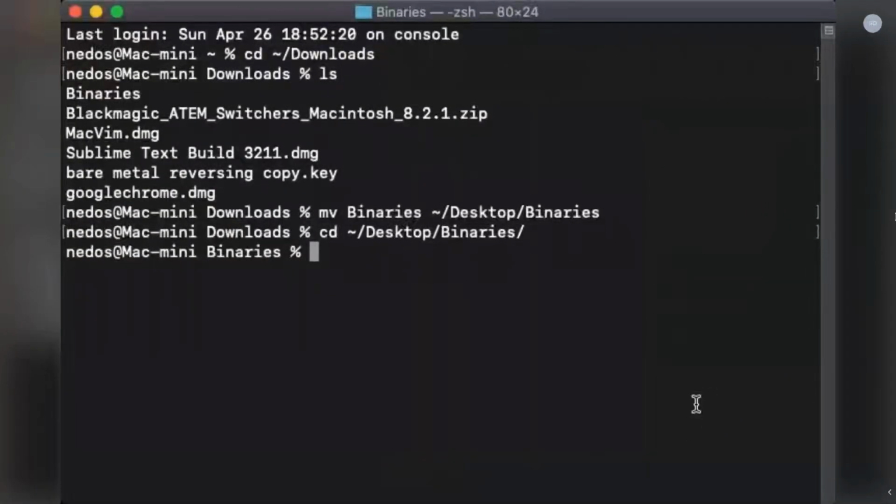Now the cool thing about this bootloader, I told you that there's a UART bootloader. There also happens to be a USB bootloader, and the USB bootloader is super nice for flashing this guy. So what I'm going to do is I'm going to hit reset, and now if you know macOS, then under volumes we should see this guy pop up.